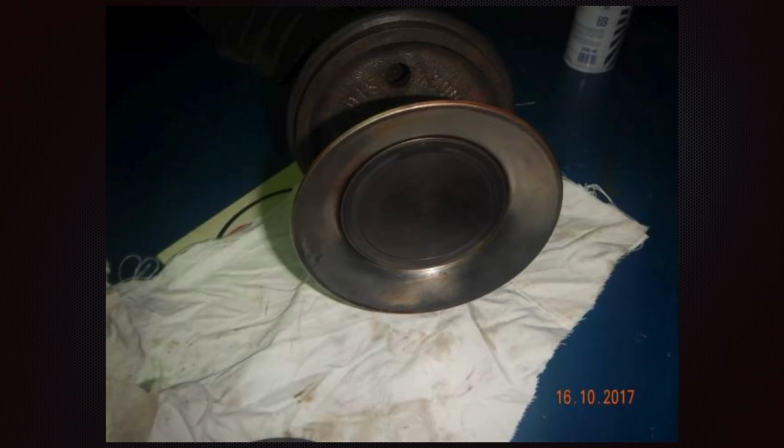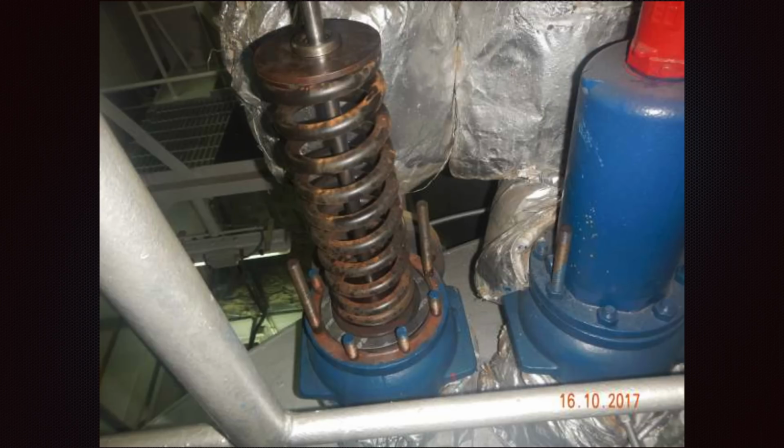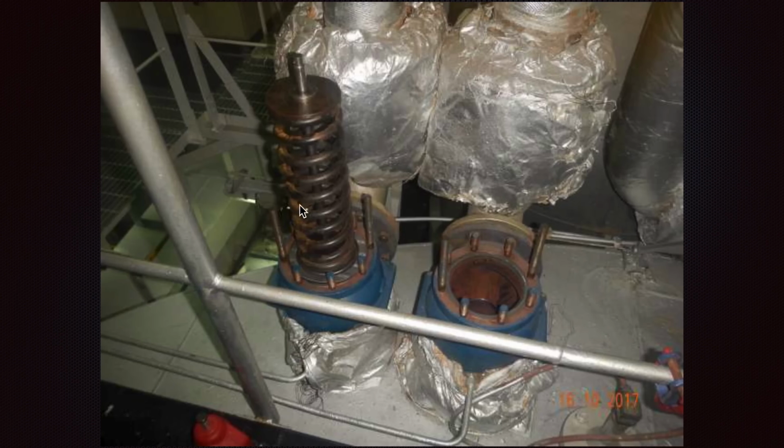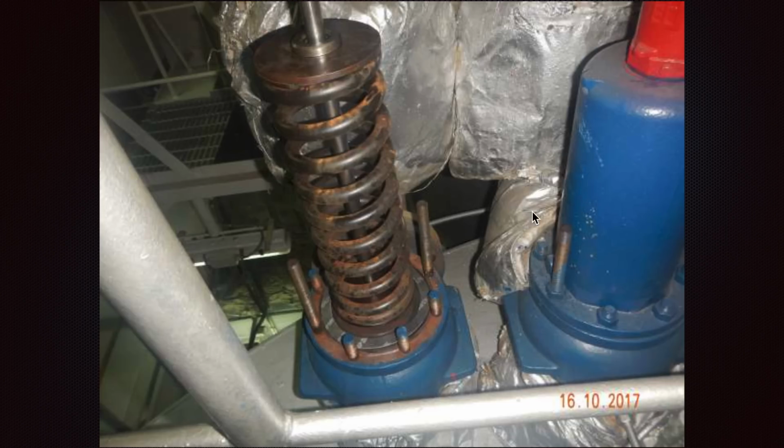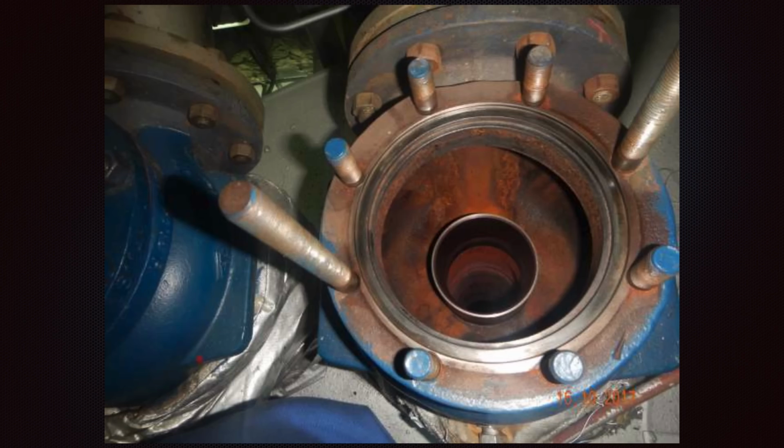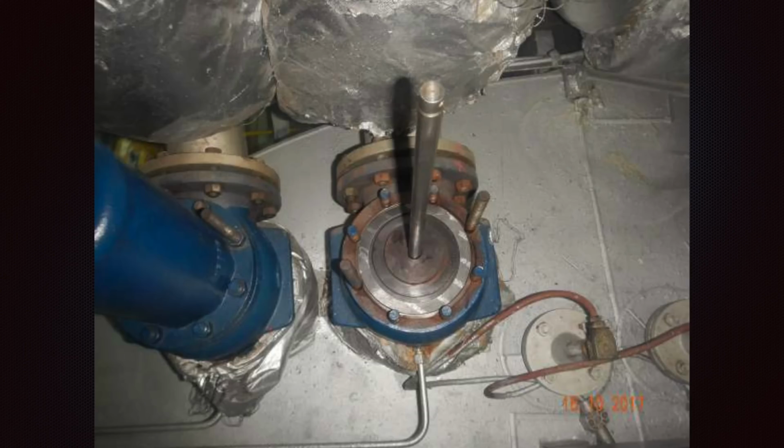Let's see a little bit more how it looks. The spring here is a really big spring, and one valve and another have slightly different settings. It can be half a bar or 1 bar, the first one opens and then the other opens, with some slight difference, but all the information that you need is here on the label or in the manual itself. And this is how you can do some lapping, but if the surfaces are good, it's not necessary to do any lapping.